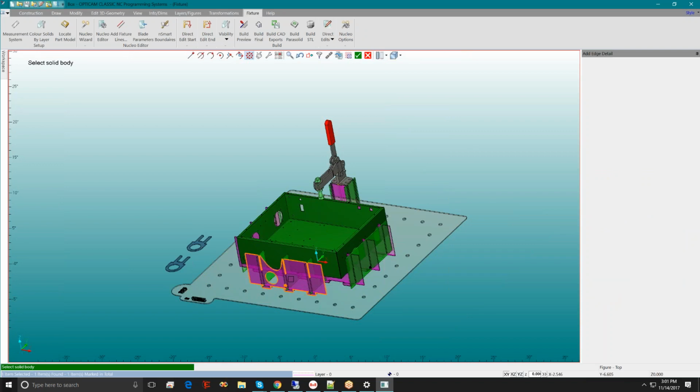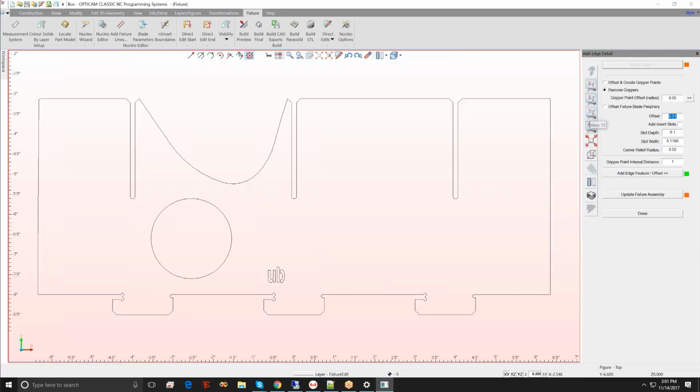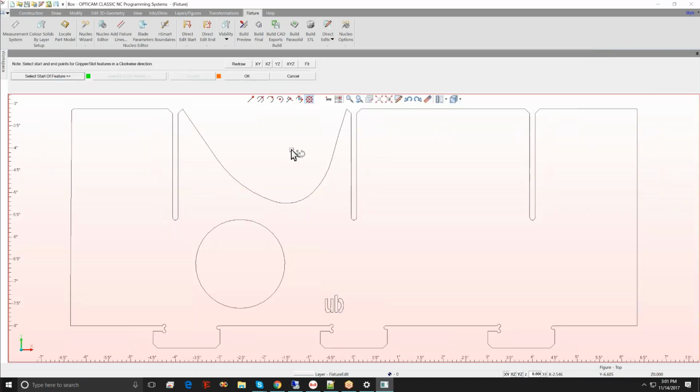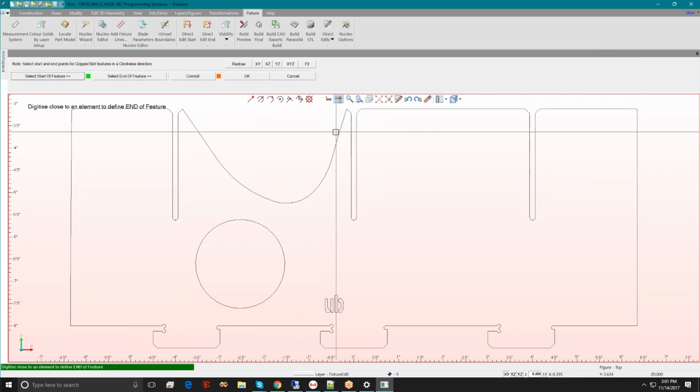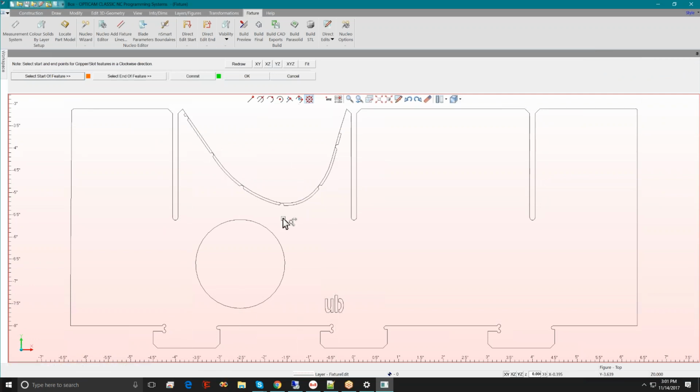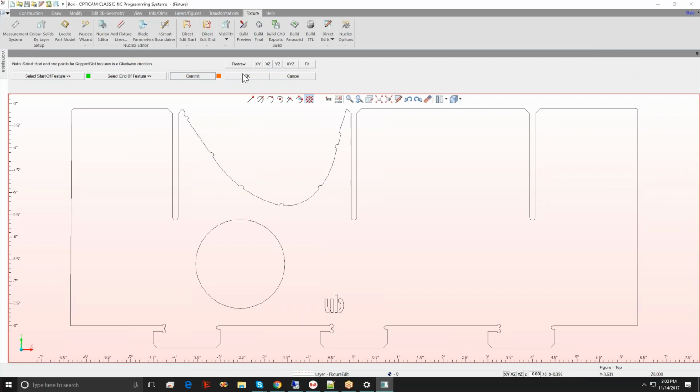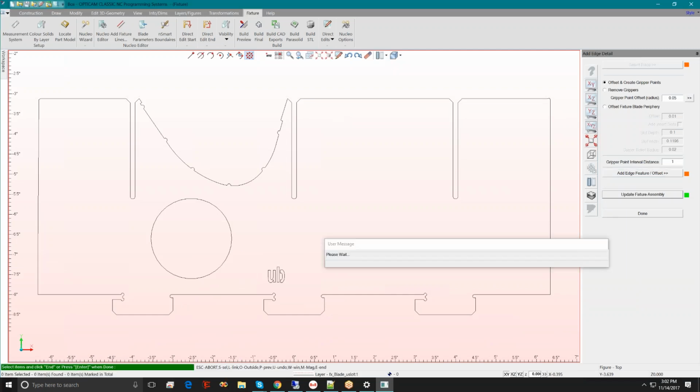This is my copy though. You can do what I talked about, these grippers, in certain points. Let's just try it. Add. So I'm saying a gripper every inch, and I'm going to say select the start here. So from about here to about here, put these bumps in there. So I'll commit those. Click OK. Update the assembly.